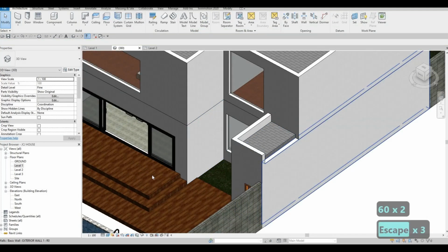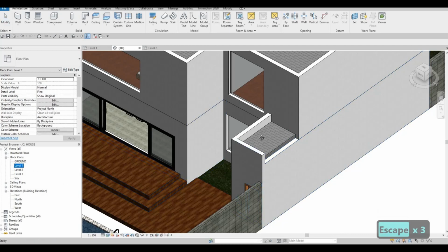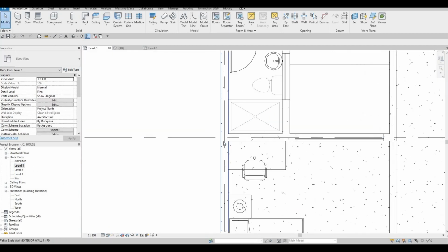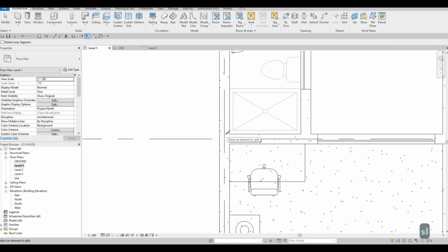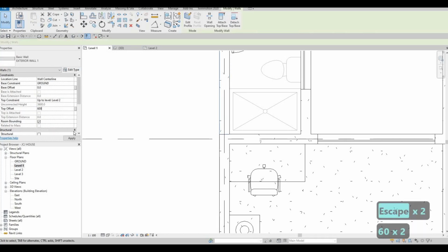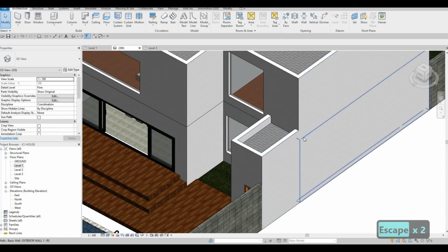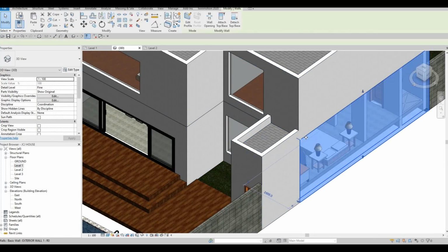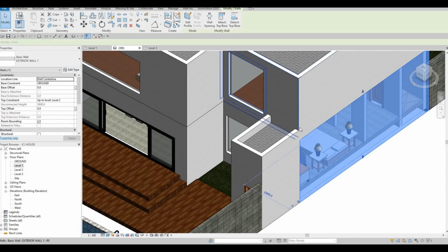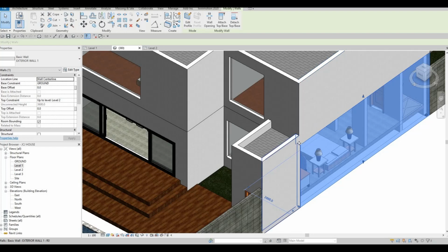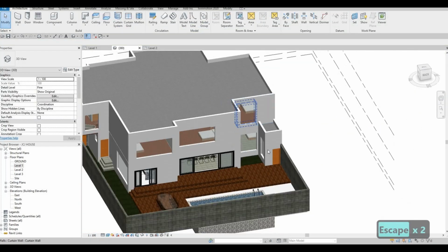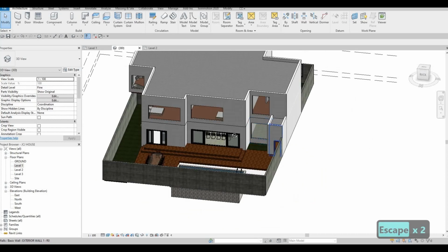So that's good. What we need to do here is we need to go here, we need to split so that we could select this up to 600. So the reason for that is so that not all of this will go up, and then it will overlap and it's gonna keep on blinking. So we need to split it so that only this part can go up. So that's called split element.